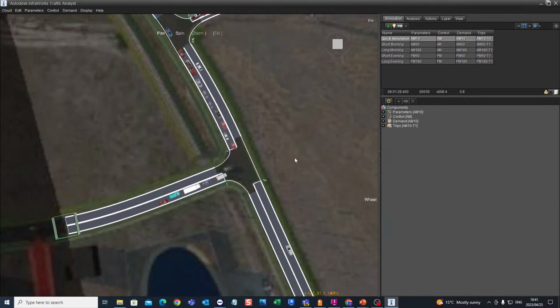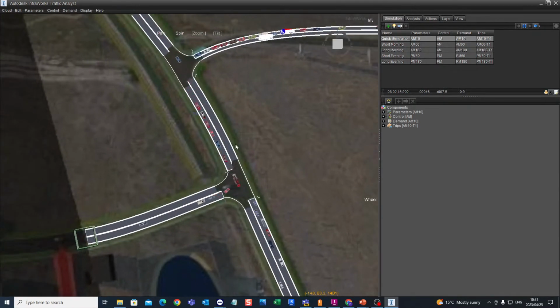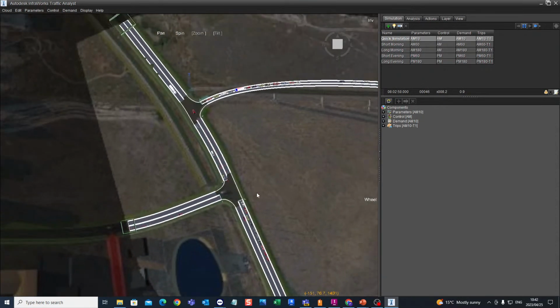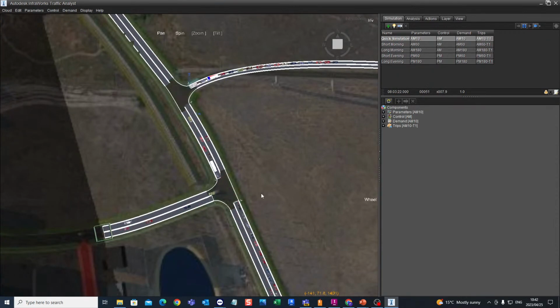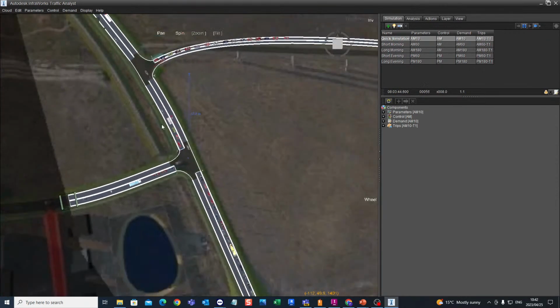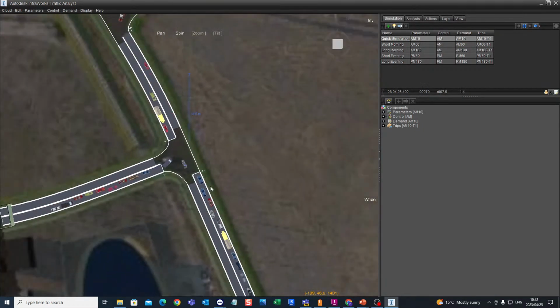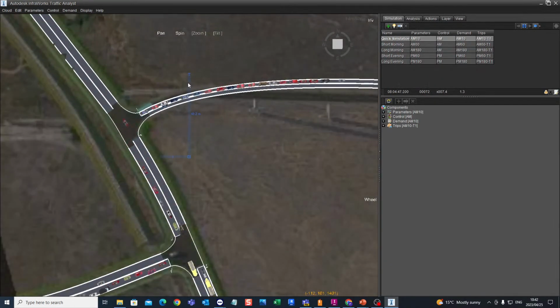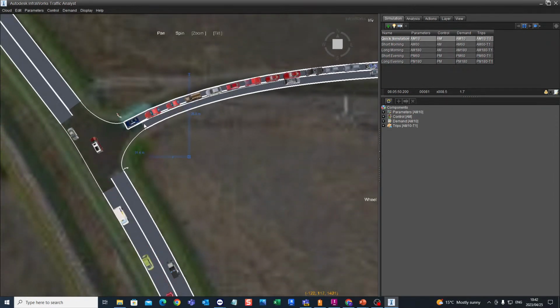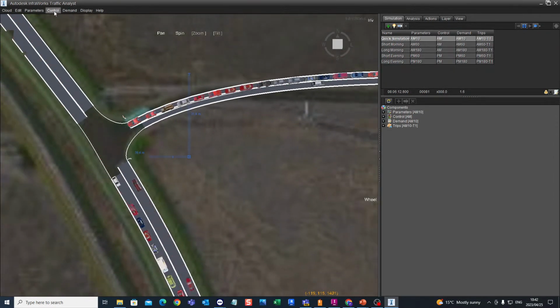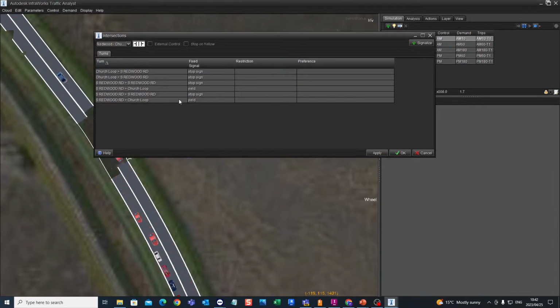Right, so there we can see this now alleviates the traffic jam that we've got at the left hand side, and traffic is building up at the top. And so perhaps this, yeah, that's getting a bit heavy as well. So maybe we need 2 lanes. We'd have to go and have a look at that situation. But it's very good that one can check the design of the road, if it's 1 lane or 2 lanes or whatever it is. And that you can do through the control of the intersections.